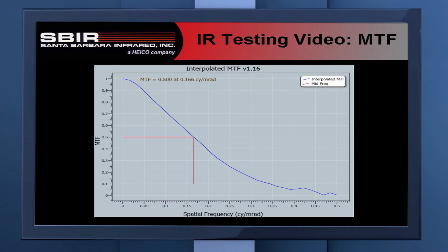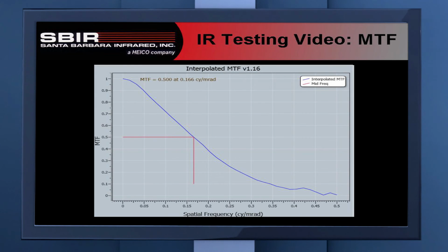This effectively higher frequency sampling curve gives us a result that doesn't impact our Nyquist limit. That's still the limit of the system. But the effective sampling limit goes out much farther to the right. And you can see in this curve that we take that sampling limit, and now we've moved all the aliasing impact way far out to the right, much higher frequencies.